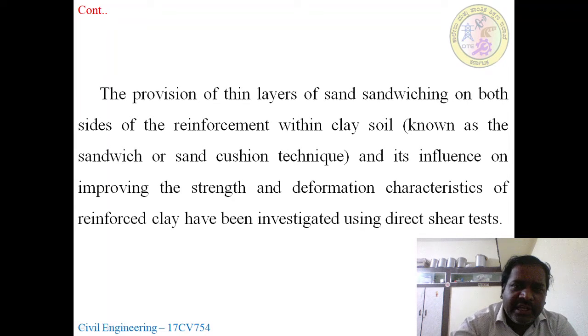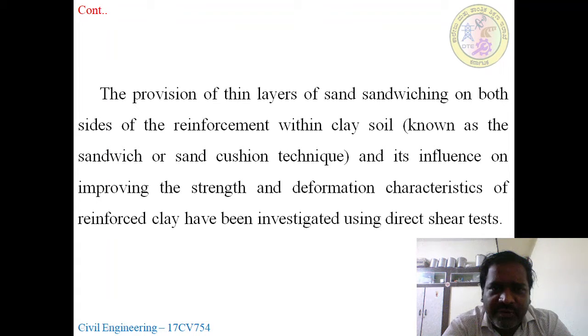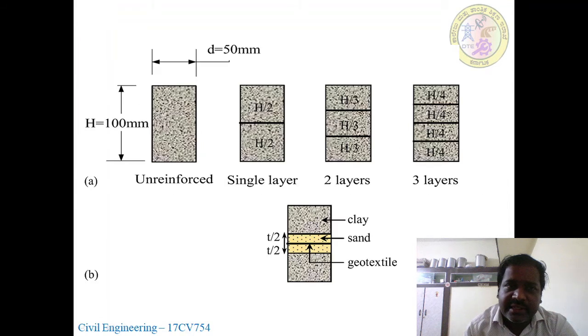The provision of thin layers of sand sandwich will affect the shear stress. Sandwiching on both sides of the reinforcement within clay soil, known as the sandwich or sand cushion technique, and its influence on improving the strength and deformation characteristics of reinforced clay have been investigated using direct shear tests. So here, one experiment was done by researchers.